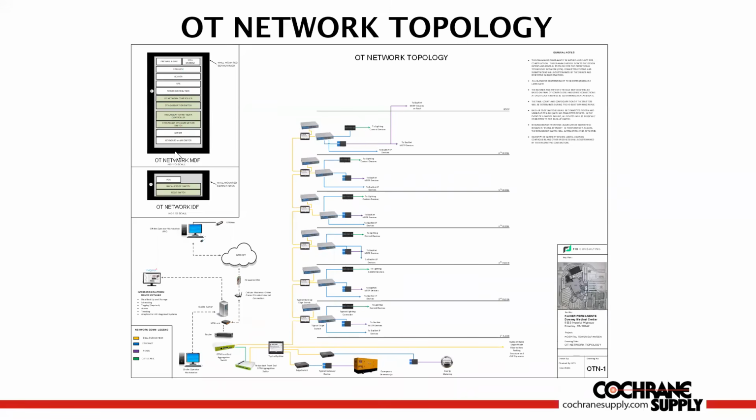These cabinets come as 4U, 6U, 8U, 10U, 12U. So if you count the components here, the contractor knows exactly what size cabinet he needs to get. And if some of those components change during the submittal process, he still would know exactly what size that cabinet needs to be. And he knows that he has to supply this cabinet, right?